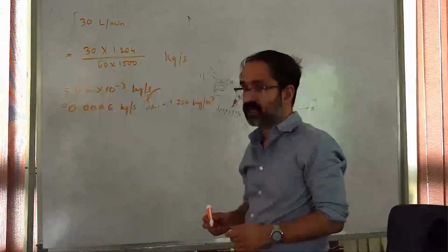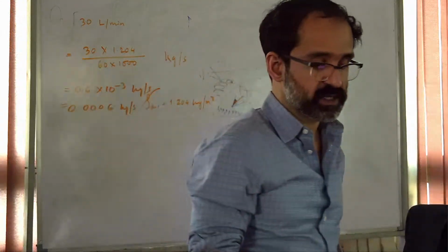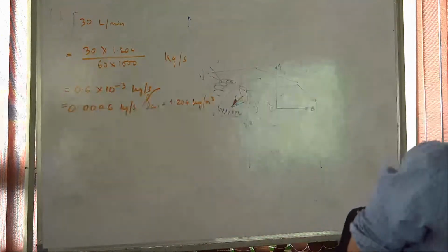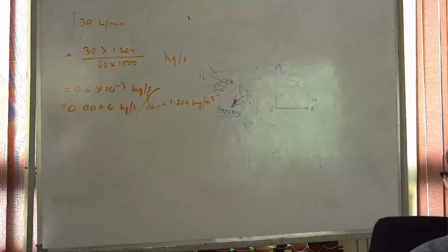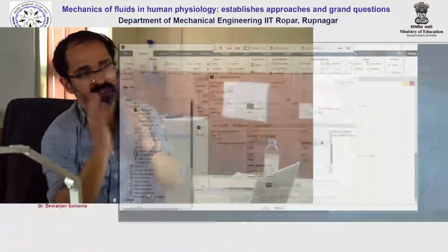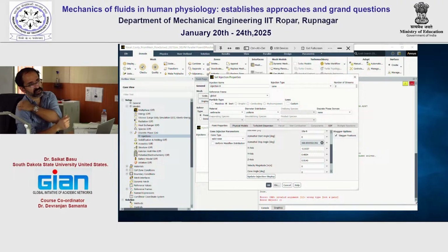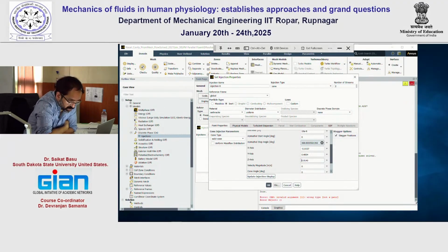Now the total angle can vary anywhere between 30 to 70 degrees based on measurements, and those measurements are mostly collected with laser diffraction studies. Do you guys have any laser diffraction setup anywhere here? They pass a laser sheet as the spray is going out, and they can get both particle size distribution and things like cone angles.